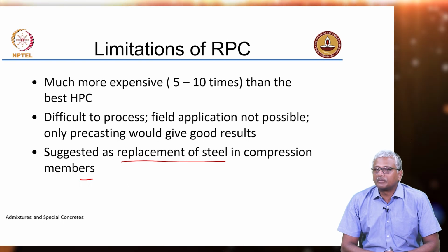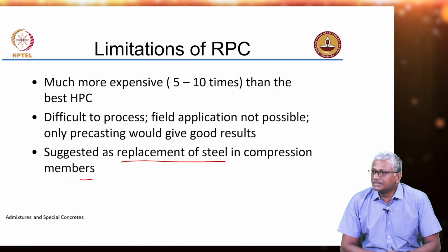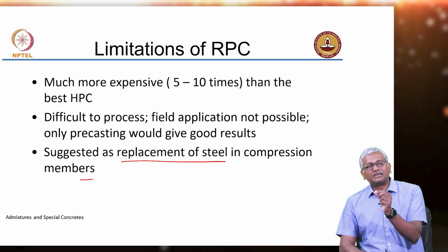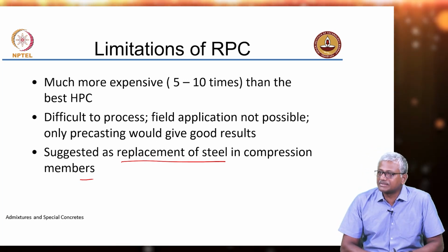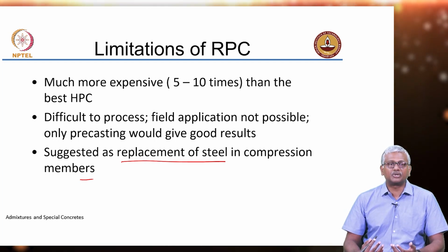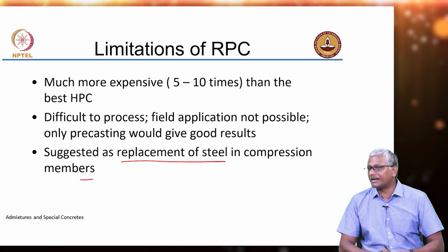May not be a big problem, steel fiber corrosion, because there is no connectivity in steel fiber. Further, the aspect ratio is so small that the part that is corroding is not really going to be able to stress the concrete significantly. And already your moisture penetration into high strength concrete is so low that you are not really going to sustain that reaction for too long.